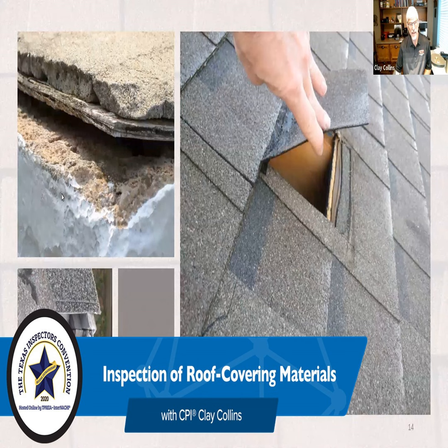But if we have drain systems like gutters, whether it's integral or installed on the outside against the fascia, we see problems with those all the time. It can cause overflow, it can cause damage to the roof, it can cause many problems. And then flashing, of course, for penetrations is critical. And we see so many times that the flashing, which is intended to keep water out, is the very source of the leak anyway.